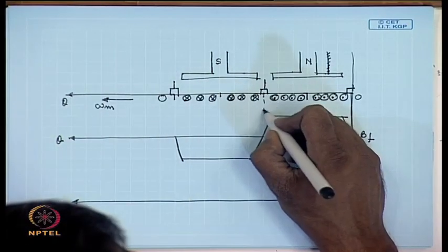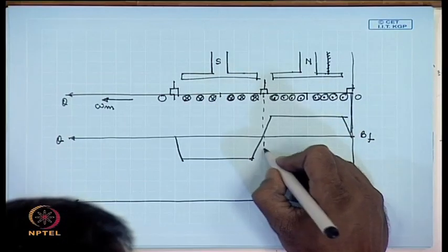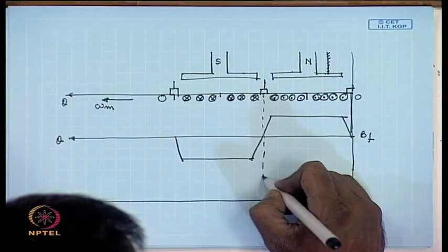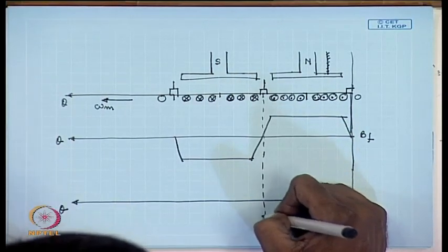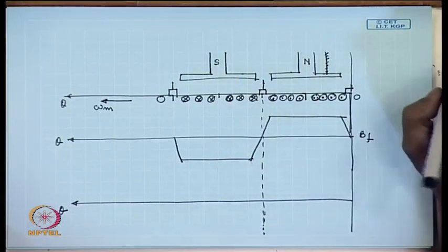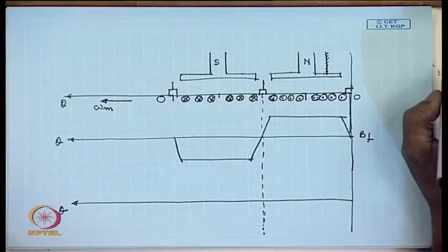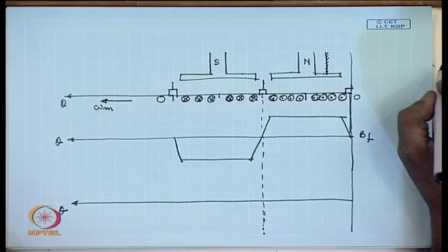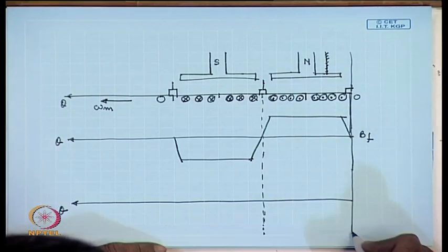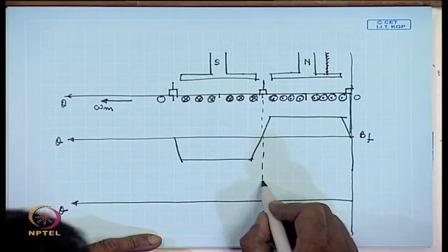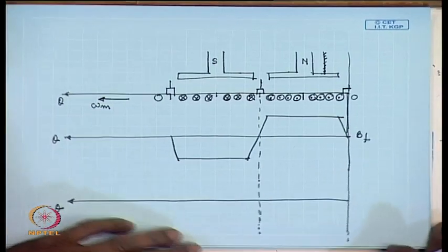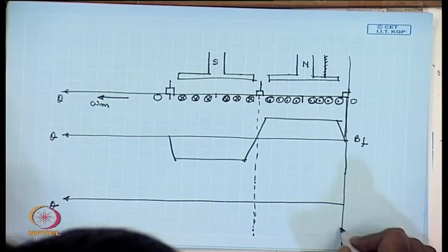The MMF, magnetomotive force, which is given in a closed path by the current enclosed, will be a triangular waveform with its peaks coinciding with the brush axis.